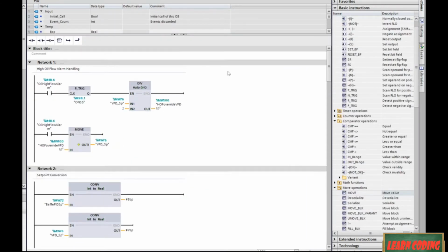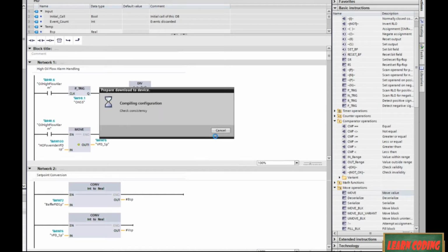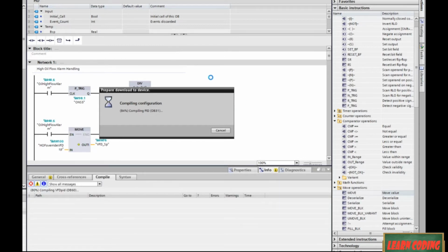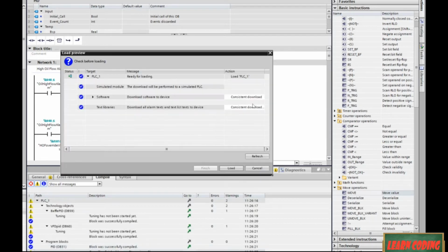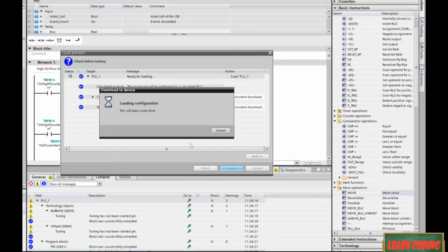And at this point, I think we can go ahead and run this thing up on the simulator and start trying to figure out where we're at. So let's do it. Let's see if it compiles. I don't think I have any logic problems in there because there was no new STL being created, and that's usually where I get screwy. So if I was doing everything in ladder or function blocks, chances are it's going to work right off. Or not, maybe not work right off, but at least compile. I usually don't get that sloppy when I'm writing that. But while I'm writing and trying to teach and talk through everything, obviously that's an added complication. So yeah, I made it this time. Everything compiled. Okay, that's cool.